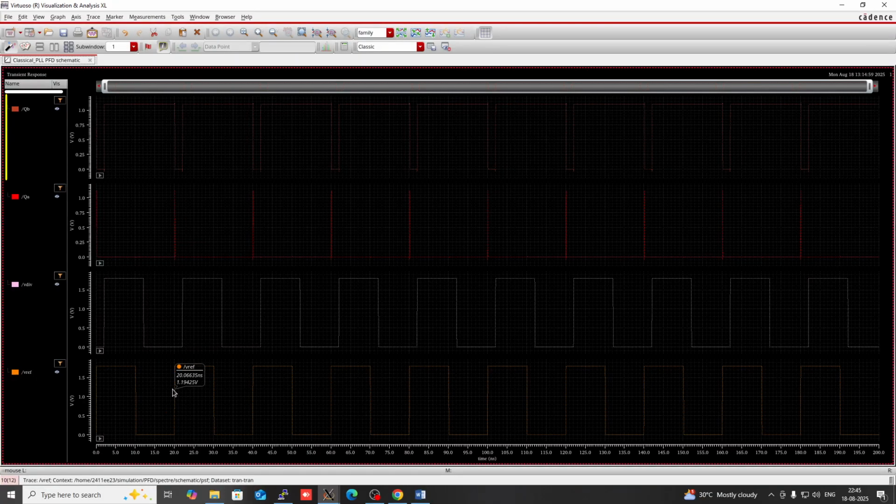So here if this is leading, then V reference is lagging, so when V reference goes high again, it goes from logic high to logic 0, and at that time one QA pulse will be generated, which is the up signal. So it is working correctly, but here it predicts that V reference will be coming here. Okay, not here.